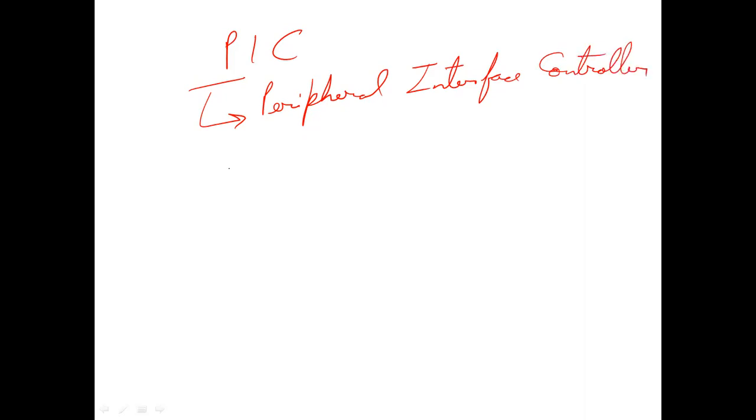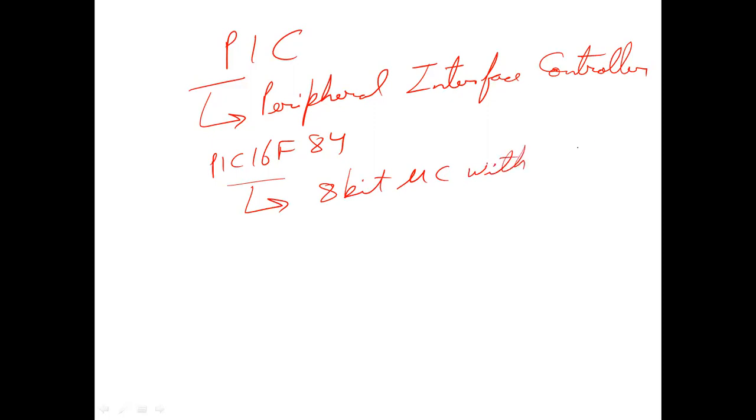Okay, and in our syllabus we have PIC 16F84 microcontroller. It is an 8-bit microcontroller with electrically erasable programmable read-only memory. And it has 13 input-output lines.